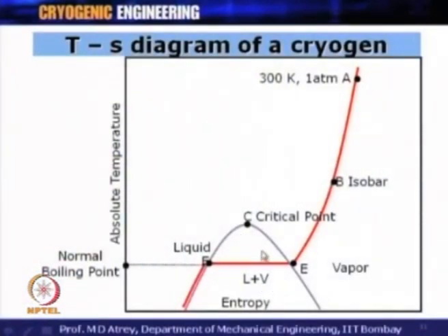And this is a very important thing: one should have the temperature of a gas less than the critical temperature and the pressure less than the critical pressure. Then only can one fall in the two-phase dome, and then only can one get liquid plus vapor, or liquid can be separated from this liquid plus vapor.